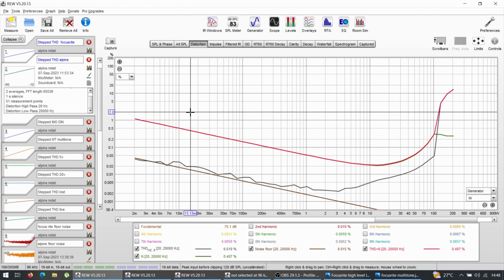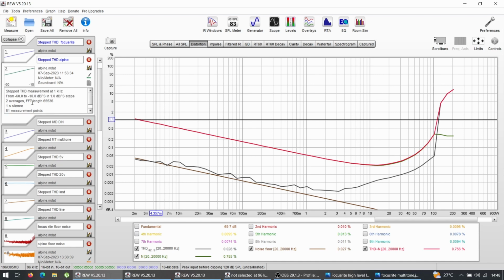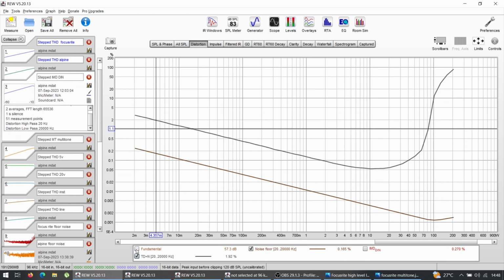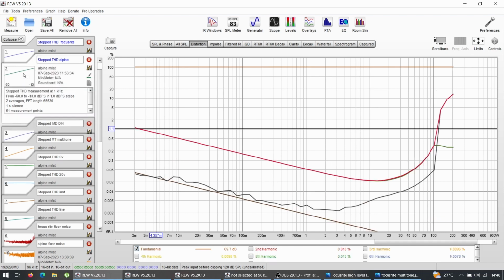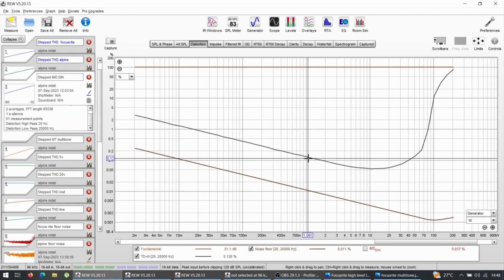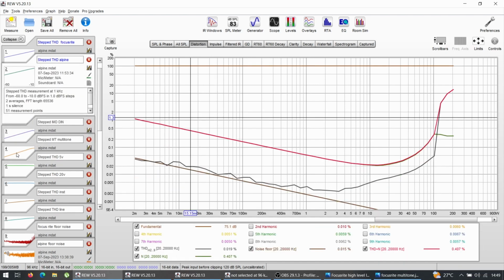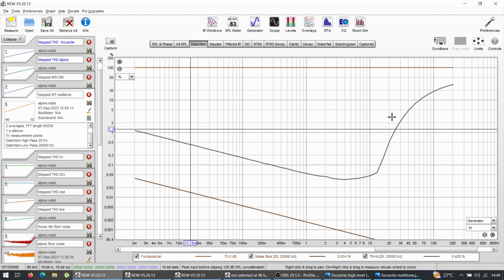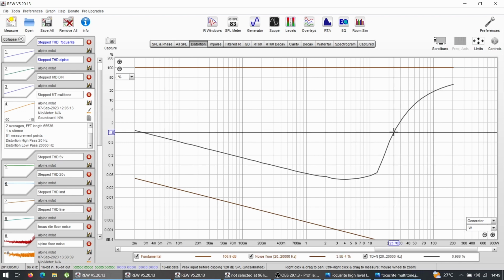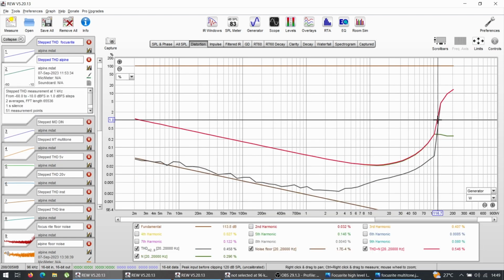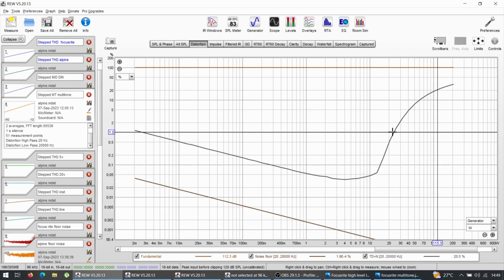So you can see, like this Alpine, for example, it has a curve like this for a sine tone of 1000 hertz. Then if I choose 2 tones, yeah, so this is for 1 tone, this is for 2 tones, and you can see straight away that the distortion increases. And this is for the multi-tone, so sine tone and multi-tone. I don't really say it has problems here, but basically up to 1% THD, it can shoot out only 24 watts, but with a sine tone, it's clean up to 116 watts. And with music, it's clean up to 25 watts. This is 1% THD with multi-tone.